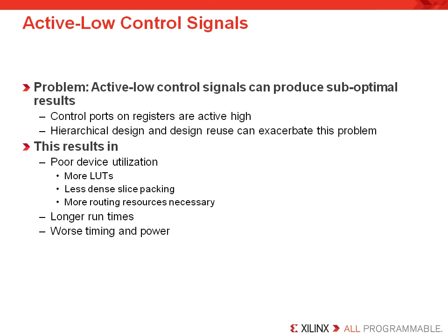And as I mentioned earlier, active low control signals are not recommended. This is because the flip-flops do not have local inversion available for your sets and resets and clock enable. And instead, inversion requires a LUT input. So this is important to keep in mind. Active high control signals are always best. So keep in mind that designing with active low control signals is an older design process or practice. So if you're emulating an ASIC or working with an older design that you're having to reuse, you might need to make some design changes right off the bat. In fact, we would strongly recommend that.